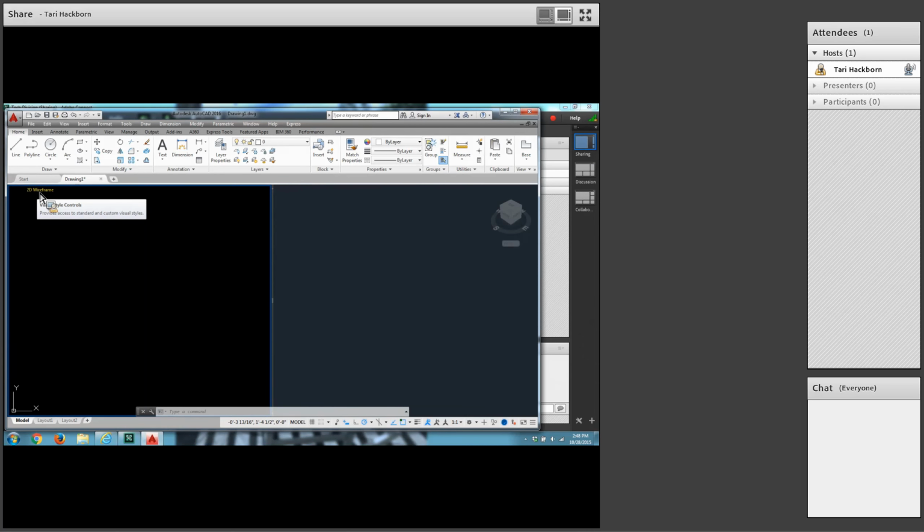Okay. Steps 11 and 12, just type the word out, facet res, for facet resolution, FACETRES. Enter. And then 4 and enter. Okay. Then type ISO lines and enter, and then 20 and enter. ISOLINES, enter, 20, enter. Okay. Now we can start the drawing.